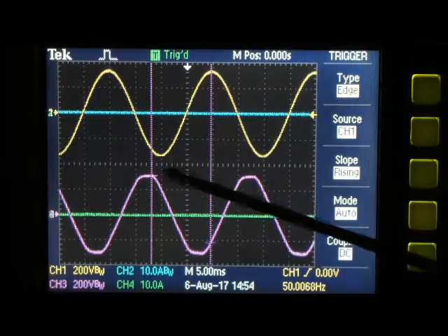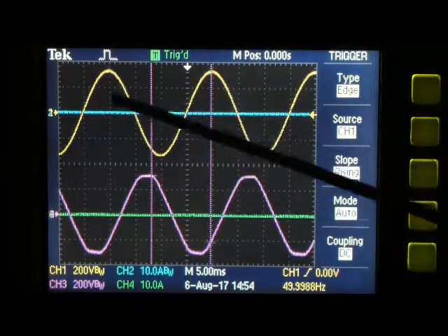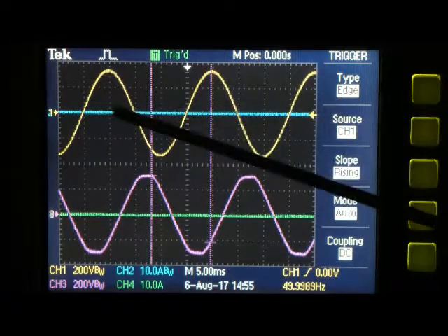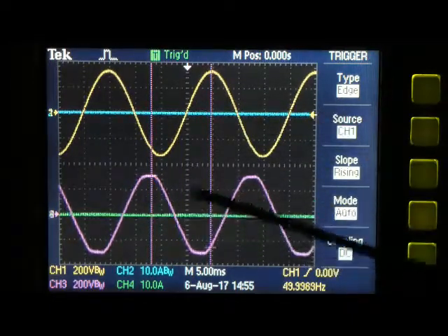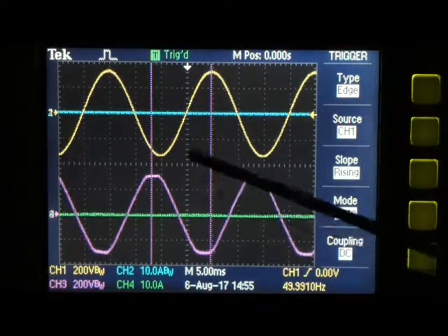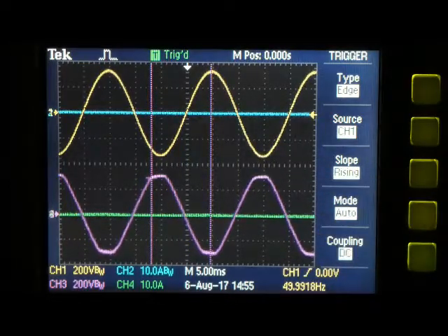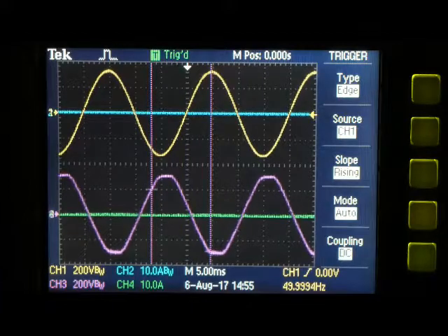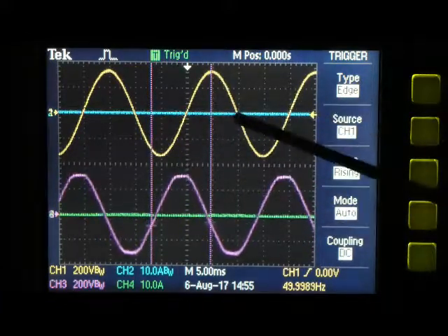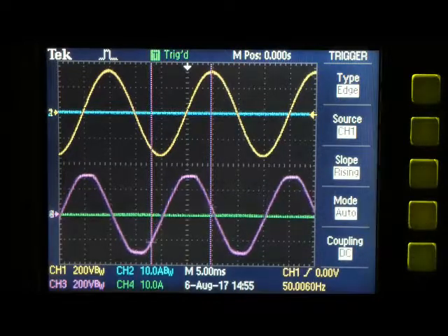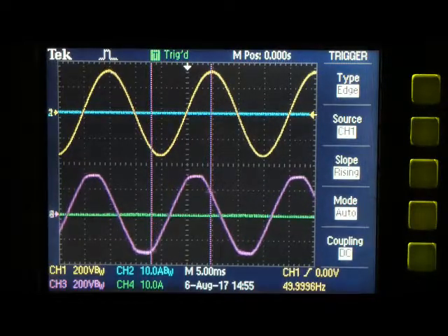And you can see also it's not synchronized with the inverter. The inverter is running at very close to 50 Hertz and the grid is just slowly drifting backwards and forwards. After a minute, which is a time set by a lot of grid connect regulations, the inverter will synchronize itself with the grid and connect to the grid.